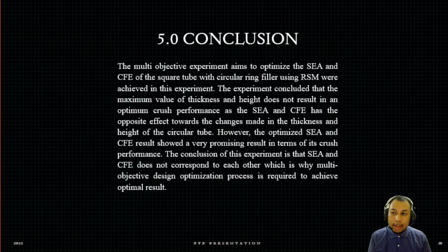Higher SEA value is seen when higher value of height and thickness is used, while higher value of CFE is produced only when lower value of thickness and height is used. So the conclusion of the experiment is that SEA and CFE do not correspond to each other, which is why multi-objective design optimization process is required to achieve the optimal result of crashworthiness of this square tube.